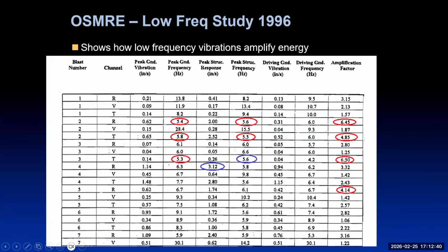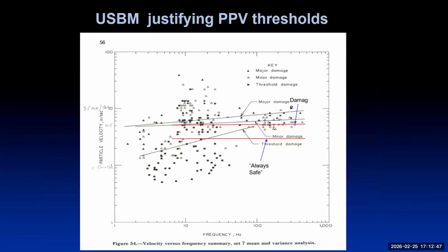So, Tom, if I could add something here, my apologies, my computer crashed a little while back. If you could go back to that diagram, that's the one. The majority of investigations actually use this measurement of peak particle velocity within 30 inches of the ground. And as Tom says, 5 inches per second or 2 inches per second are the difference between always safe and damage.